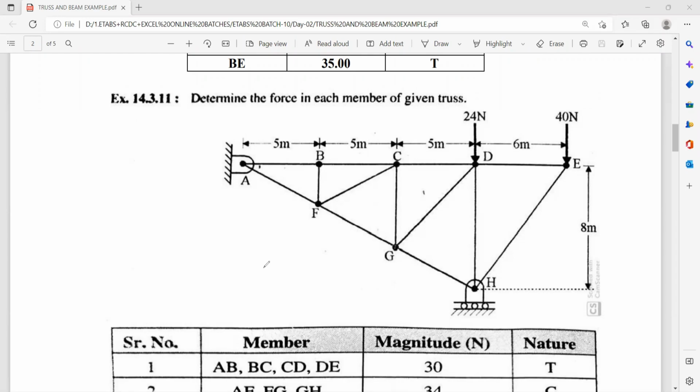Now tell me, please, how many levels are there? 4 levels. 1, 2, 3, 4. Very good. So how many additional levels? 1, 2, 3. ETABS software considers this as the base, so I am going to leave it as the base level. This is the first, second, and third: additional 3, and this is the base. So the total becomes 4, but we are considering it as 3: 1, 2, 3, and this is the base. So 3 levels will be there.